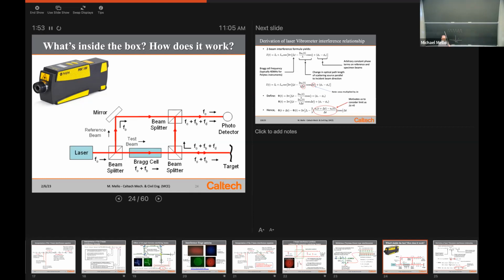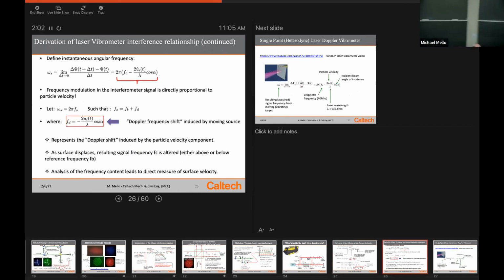And the benefit of this Bragg frequency is that now, let me shift to the next slide to emphasize it. Here is the key result, okay? It says the interferometer's output, if we're treating it as a velocity interferometer, says the phase portion that's being reported is 2 pi f Bragg. Yep, that's this, f_B, f Bragg, that the Bragg cell puts on. And U dot is the velocity of the surface. If U dot is 0, then what it sees is just nothing but the Bragg frequency on the signal.